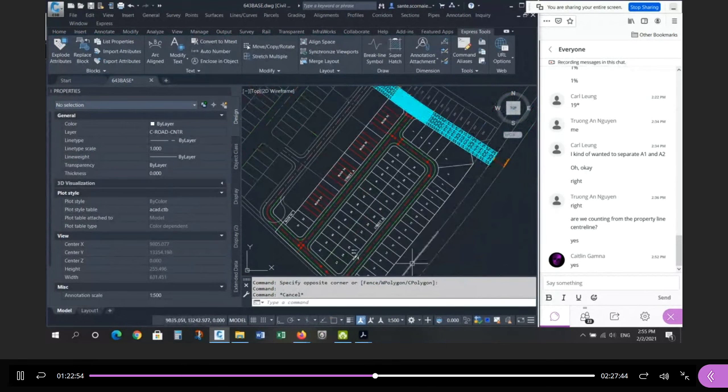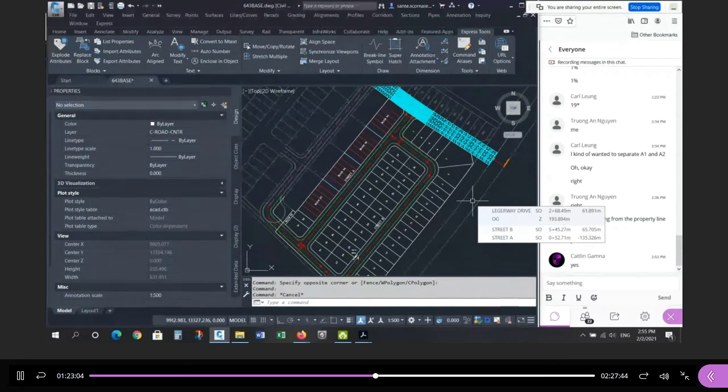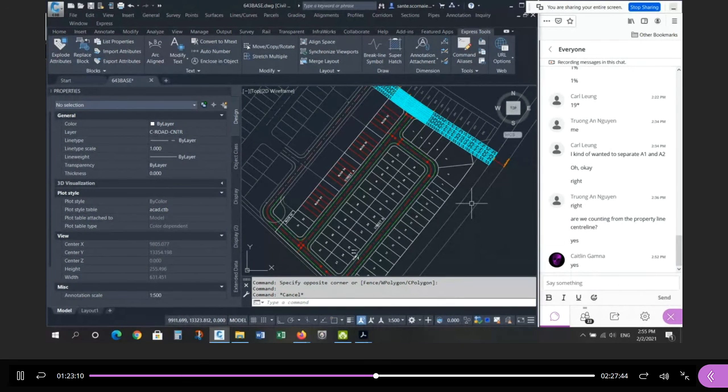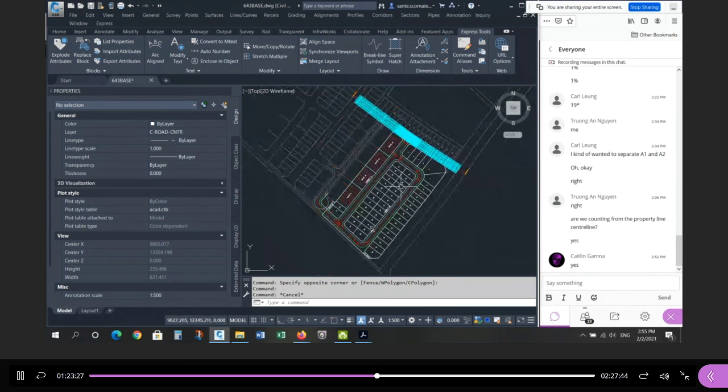And I wish I could do the same for this one, but I don't have the plan profile for this road. So then I'm going to use something different for that, right? So I'm giving you some options, right? If you have the information to recreate the corridor, that's probably the best way. If you don't, then you have to do something else, right? And we do have other information, so I'll walk you through that process. So I'm trying to give you a variety of different data types and data sources so that you can get what you need from the existing information so that you can do your proposed design. This is one method. Use a corridor of a previous design because it's not on the topo. Okay, any questions about the process or the reason for doing this?